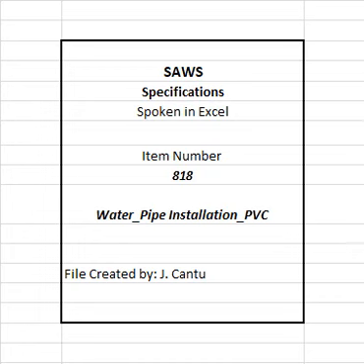The pipe shall be laid by inserting the spigot end into the bell flush with the insertion line or as recommended by the manufacturer. 3. At no time shall the bell end be allowed to go past the insertion line. 4. A gap between the end of the spigot and the adjoining pipe is necessary to allow for expansion and contraction.